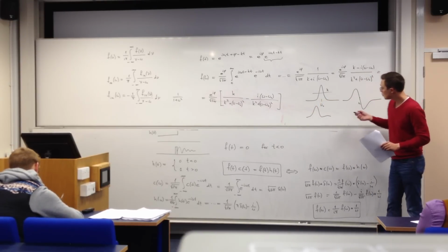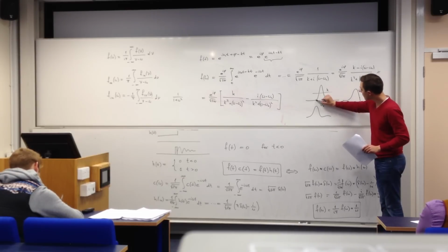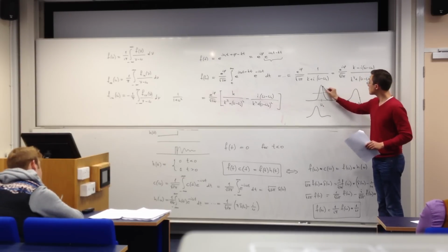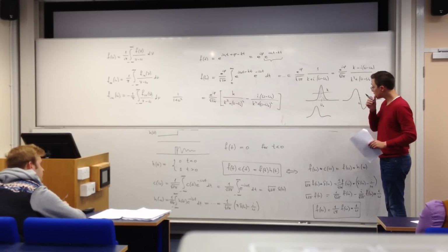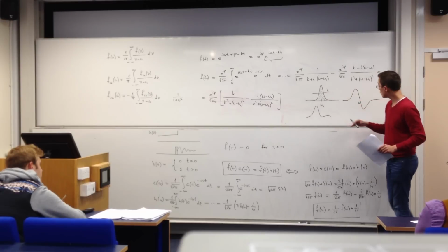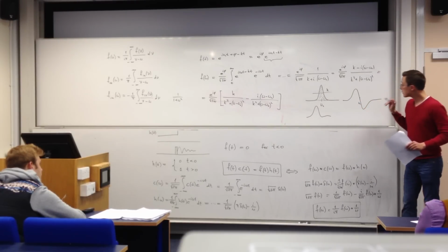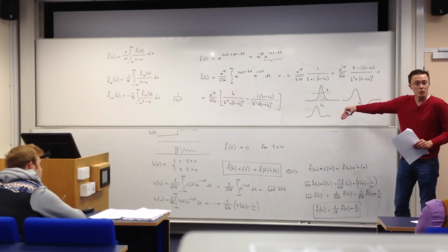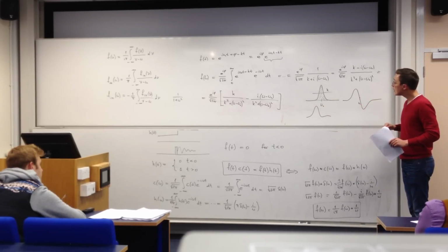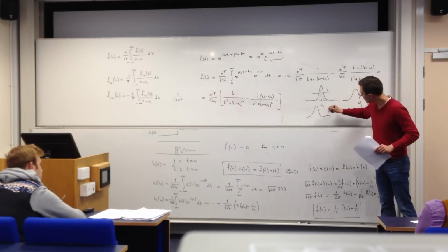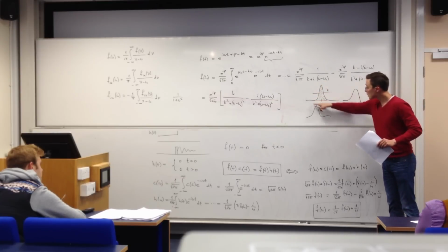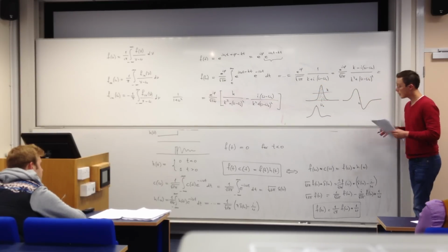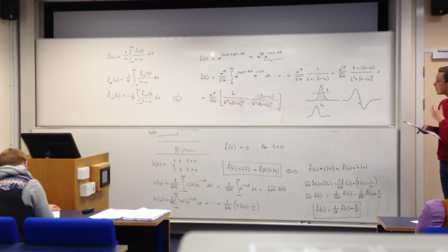And what we properly want, because we want to quantify it and therefore integrate, is for the signal to be positive, because then the integral is actually the correct integral, whereas this is a combination of something that integrates to what we want and something that integrates to 0. And in the extreme, it would simply integrate to 0, or the integral will become unpredictable. So before that, also it's difficult. The maximum is shifted here relative to the omega naught, and so on. So we want to only keep the real component, because it is the component that contains our information. And so the process of doing that is called phasing.